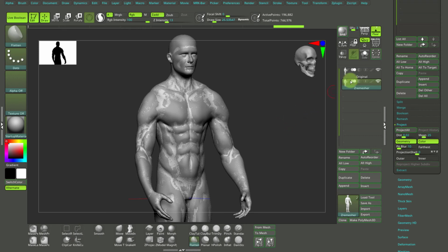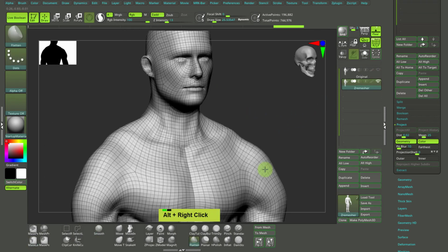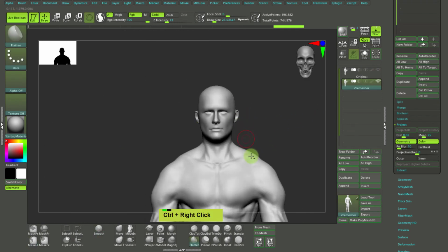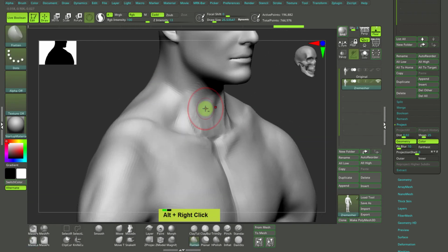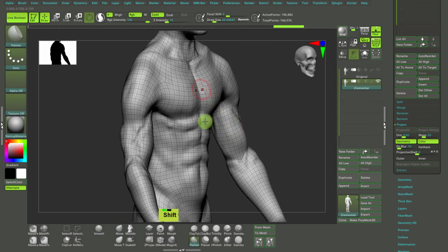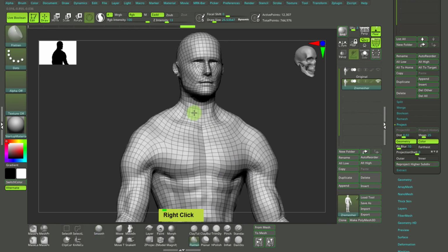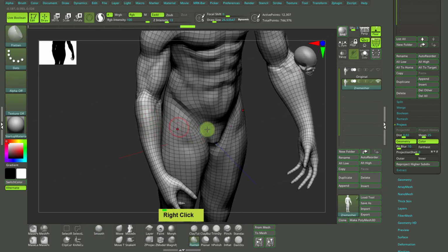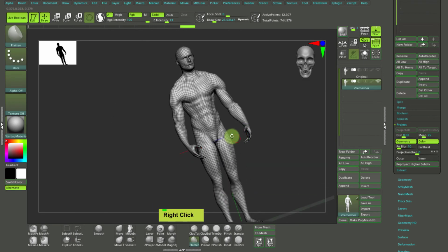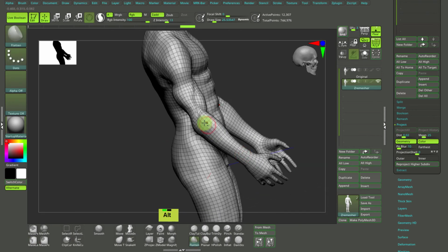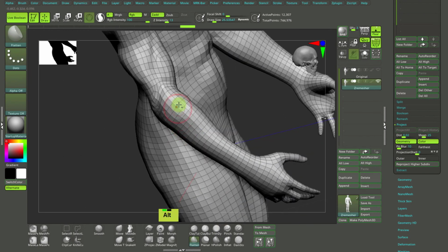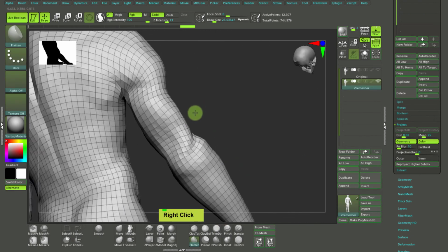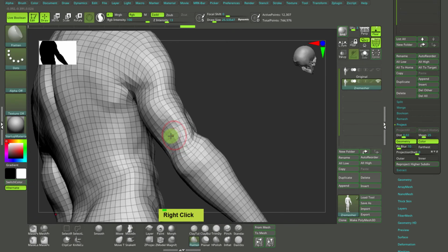Instead, I will go and turn off the original model and see this one for myself. So here we are. You can see there's not much welding going around. All right, so this is a nice single mesh. Can you see, Shift D? This is even, there's no trace of welding or cutting or anything like that. Now how to fix things. Here we have some jagginess, here's this cavity at this low resolution.